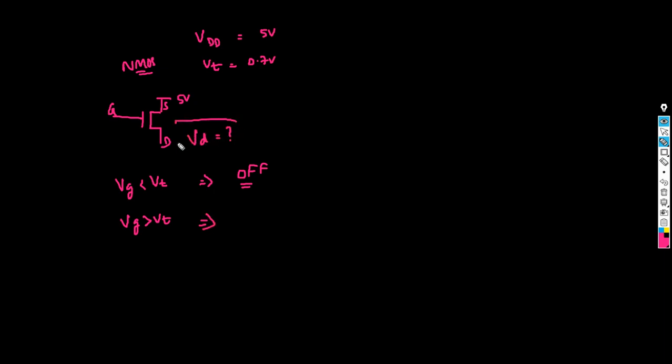You need to understand that your VD is going to be VDD minus VT. What is going to be the voltage here? So 4.3 volt.